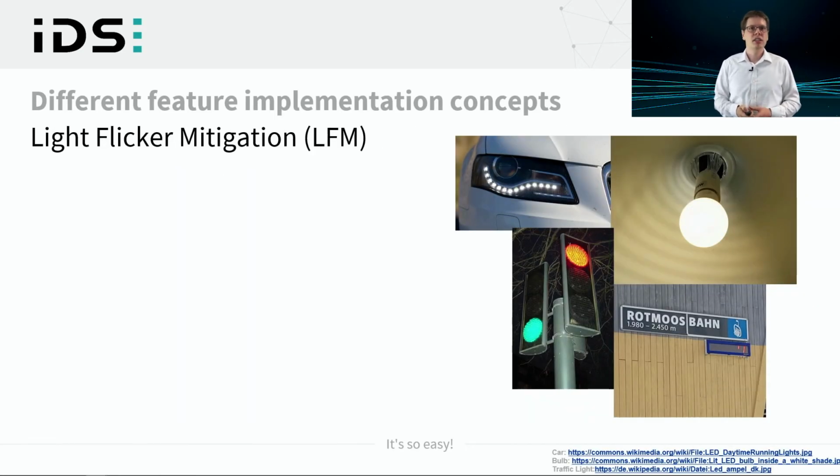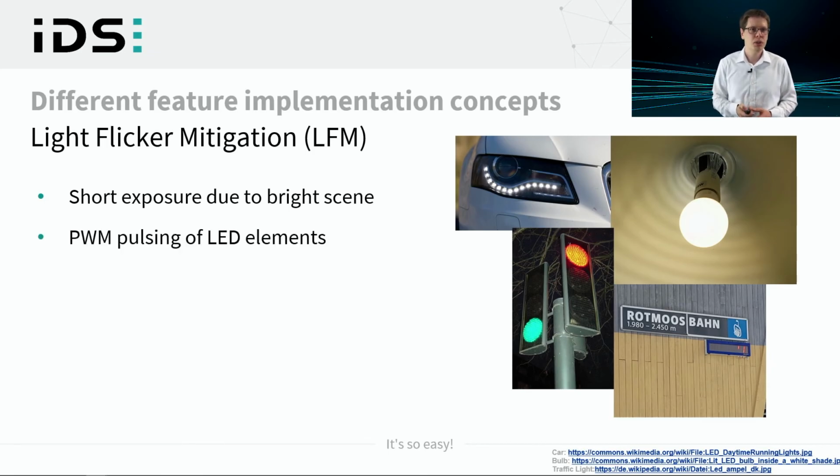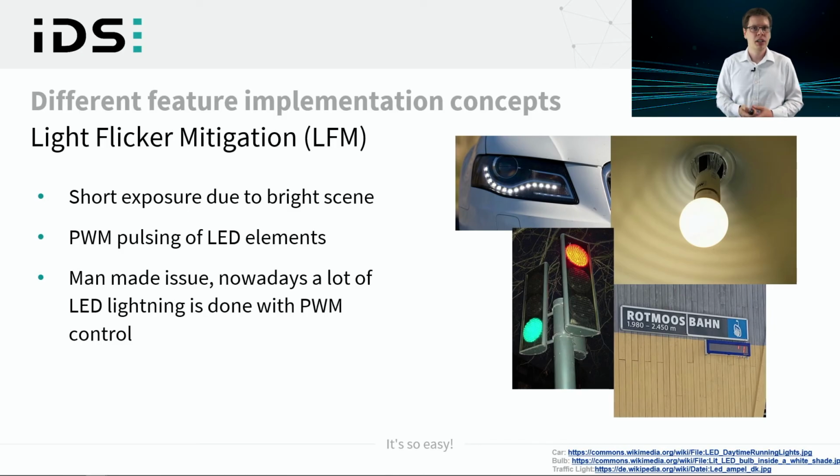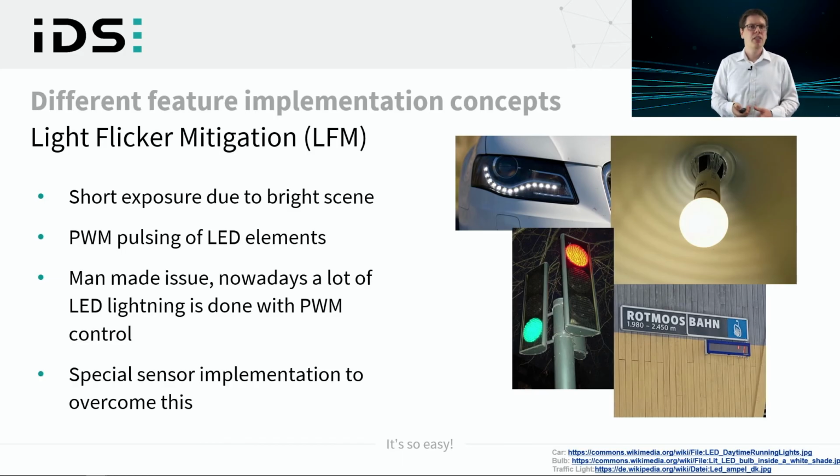The cause is a short integration time in combination with fast pulsing light elements. This is a man-made issue, and there are a lot of situations where this might lead to wrong evaluation results. There are special techniques at sensor level for light flicker mitigation.